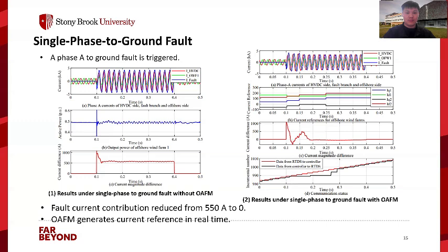The OEFM controller sends the reference values 3 times during the fault, which means 3 rounds of optimization. The average time is 54.3 milliseconds. The testing results validate that OEFM works in real time to reduce the fault current contribution from offshore wind farms.